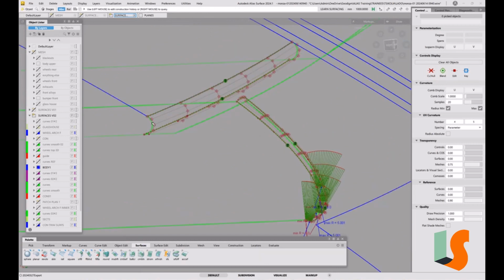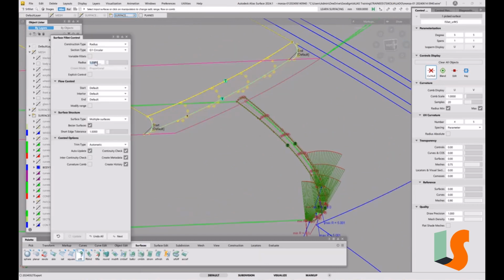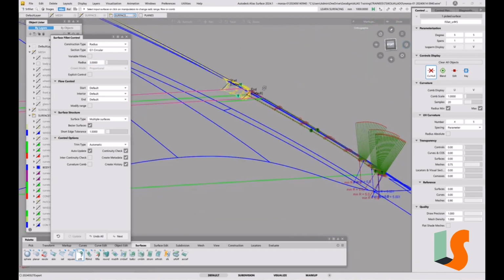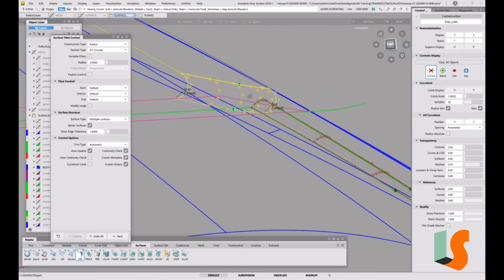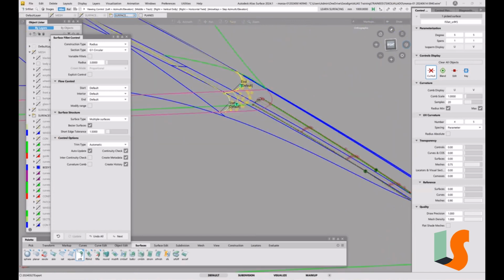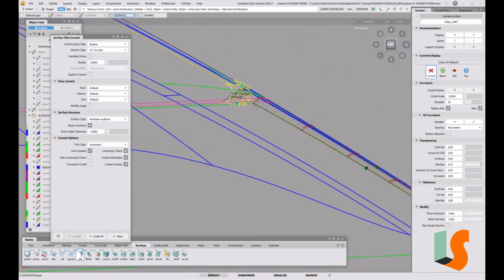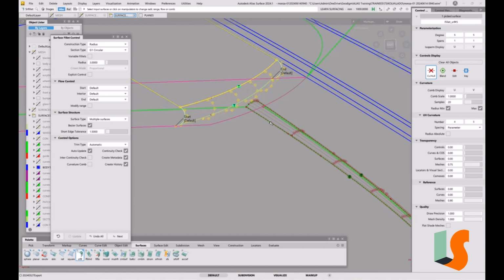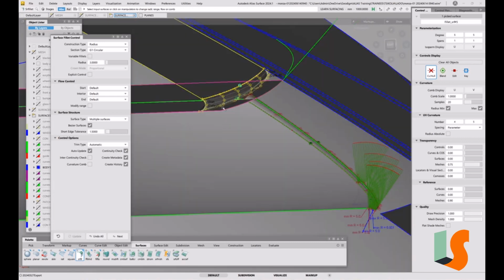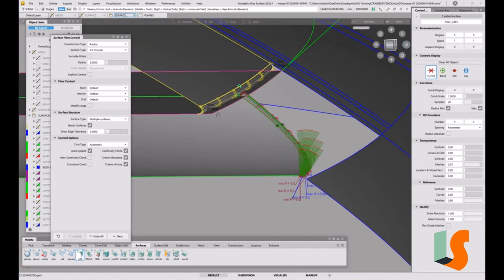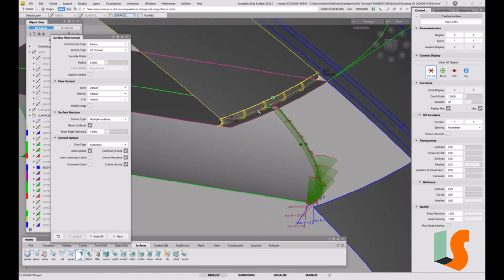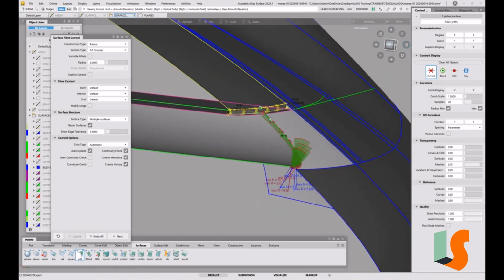So one way around that would be to say, right, let's make that a smaller fillet. Let's make it 3 mil, and actually that's a lot closer in terms of size. I mean, in terms of the bottom edge there, because we've got to get around this corner as well. So we've got to think about how this is going to go around there, but also the fact that it's cutting back that surface so much. Now, because I've got history on there, I don't think we should go below 3 mil. That's a very small fillet.